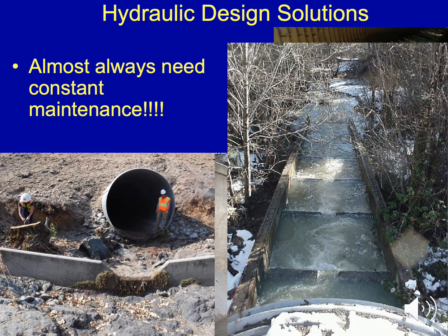For a long time, the standard approach for our hydraulic solution was to create fish ladders. And now, by and large, both DFW and NMFS have moved away from these approaches. These are really difficult to get the hydraulics right at a wide range of flows. And when you don't have a fish passage solution working at a wide range of flows, you really preclude the timing of the fish when they can move through. These are also phenomenal debris catchers. And they get full of debris and then they quickly become nearly complete barriers.